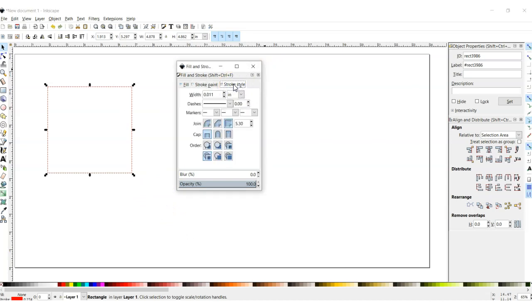For stroke style, this changes a few times throughout our design process. You have your units. Let's leave it on pixels and put it on 2 pixels for now so you can see it. Later on, when our whole drawing is complete, we're going to select everything that we've made, come back here, and we're going to make it PT and 0.072. This is crucial. This is the width of the laser cut, and the laser machine will not cut anything unless it's in this specific width.